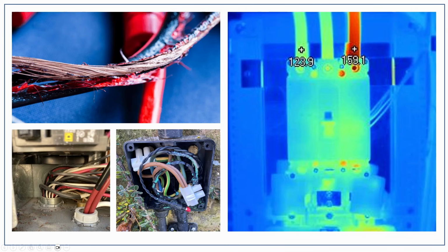The other thing to keep in mind is that once you terminate these conductors, if you've exceeded the ampacity of the conductor, that conductor is going to be hot. It's going to start to degrade the insulation. It's also going to create hot temperatures at the termination point, degrade the termination point, degrade the plastic of the breaker or whatever other terminal we've connected up to, and create hot spots and resistance, which will further cause more heat and down the line a fault there. So lots of reasons why we want to keep track of the ampacities of our conductors.